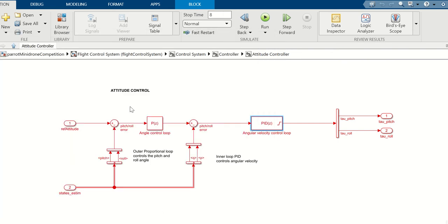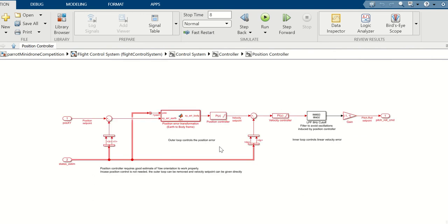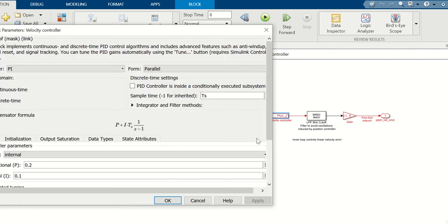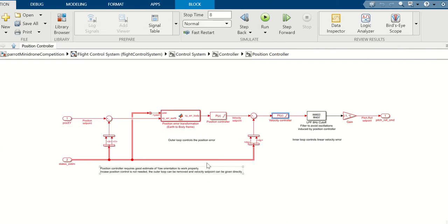But then in addition to the pitch and roll, there's another box. This box here is an XY coordinator. So in order to change an X or Y, you pitch and roll the drone, and then it moves in that particular direction. This is a slightly more complicated box, and it has also got some PID gains in. If you look at that box there, again, it's got a PI controller in there, it's got PI gains in there. So you can change those.